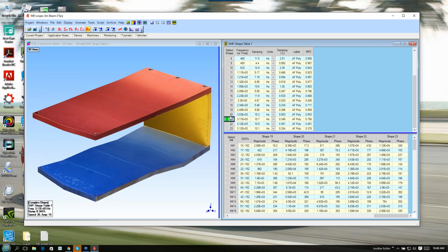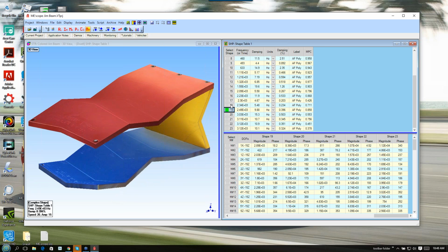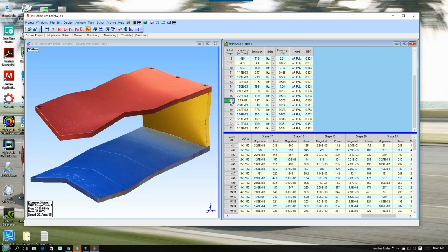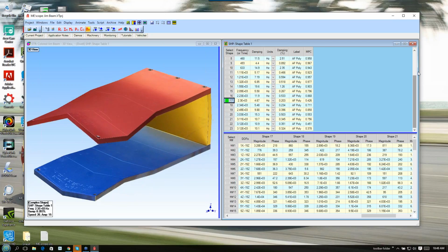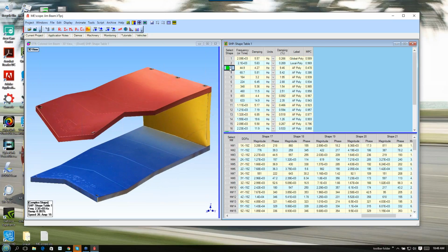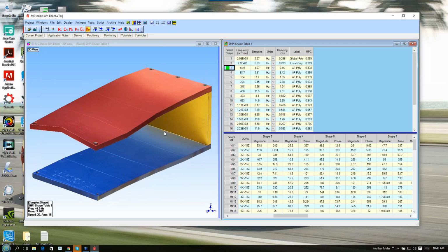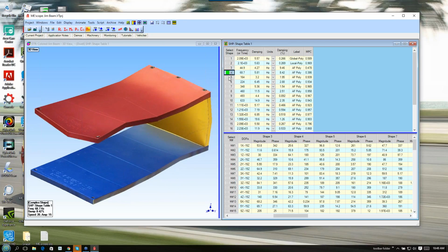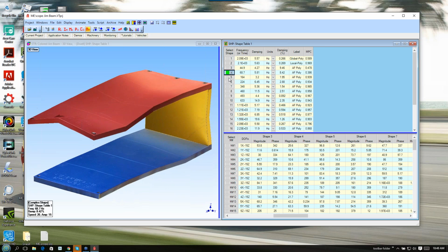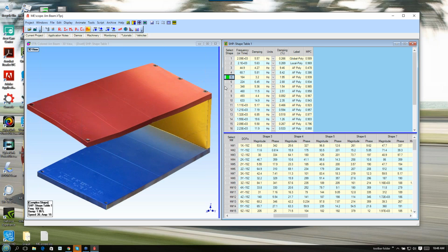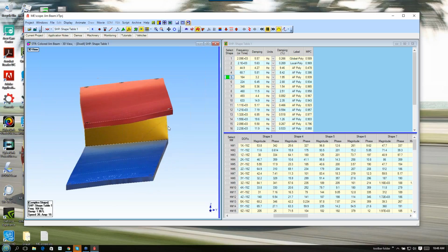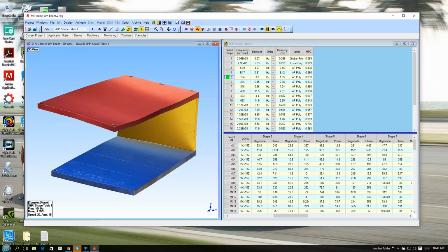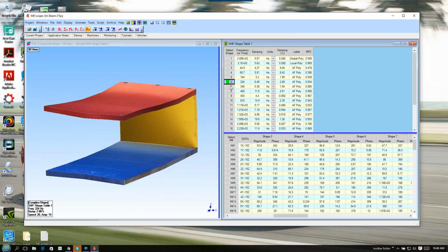So if I just blindly go through and fit my data, I may get some very strange looking mode shapes. Let's go down here and look at it. Now there is a rigid body mode way down. We didn't fit anything down that low, or we didn't go down there and look, but there's our first flexible mode. Not bad from the stability curve fitter.